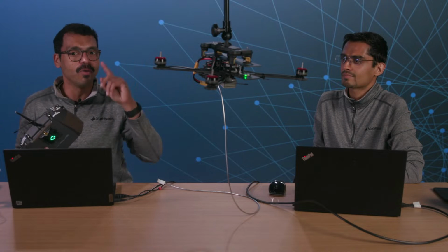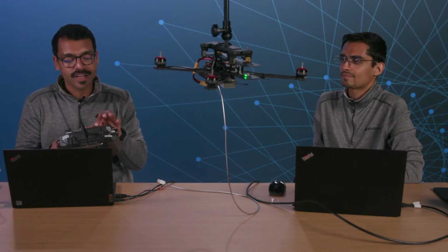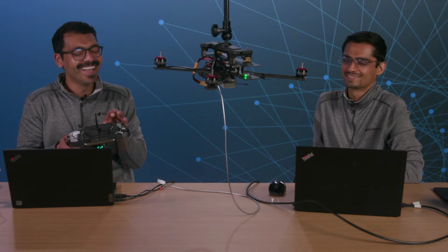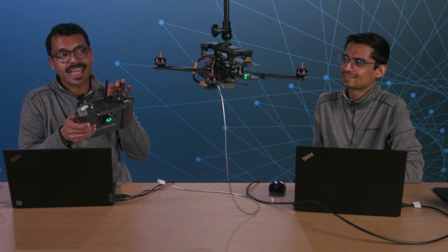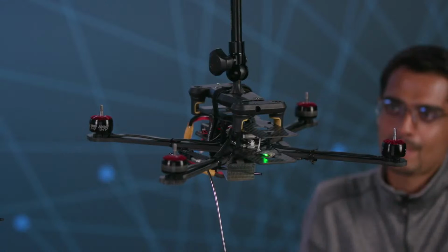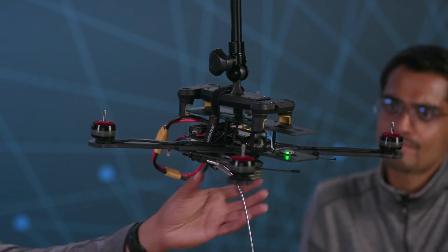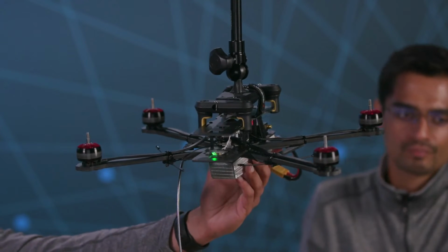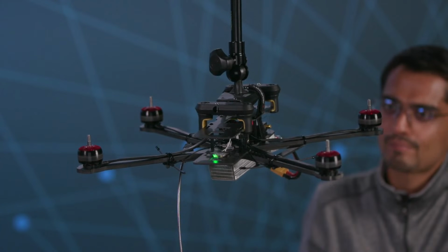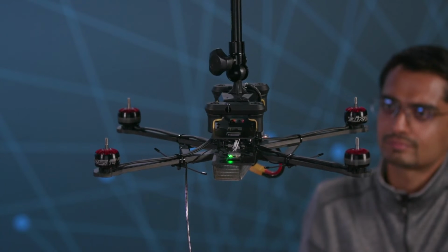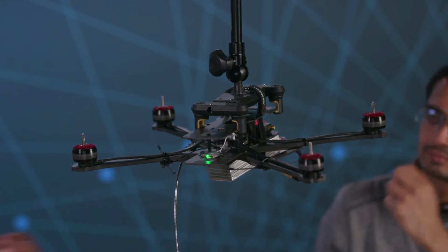See, I'm using the moments of the actual motors to move the drone because I don't want the propellers running here. We don't want to break the studio. But if I use channel 8 and enable yaw control, it's going to apply sufficient moment to bring it to the center. I can disable that, move it to this side, and then enable yaw control again, and it's going to try to bring it back again. So let's do that again.